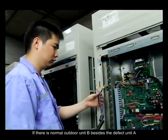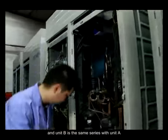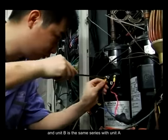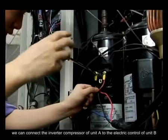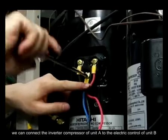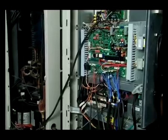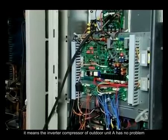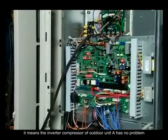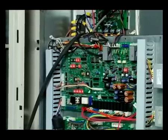If there is a normal outdoor Unit B besides the defective Unit A, and Unit B is the same series as Unit A, we can connect the inverter compressor of Unit A to the electronic control of Unit B to see if it can start to run normally. If the outdoor Unit A can run normally now, it means the inverter compressor of outdoor Unit A has no problem. But the electronic control probably has a malfunction.